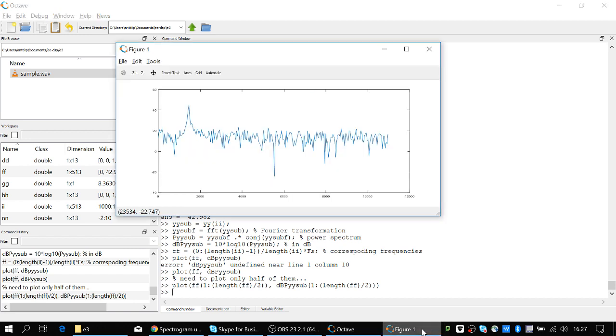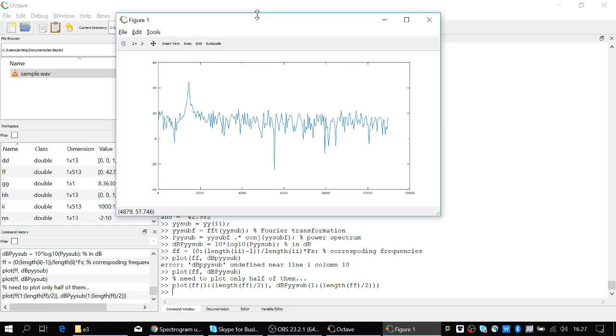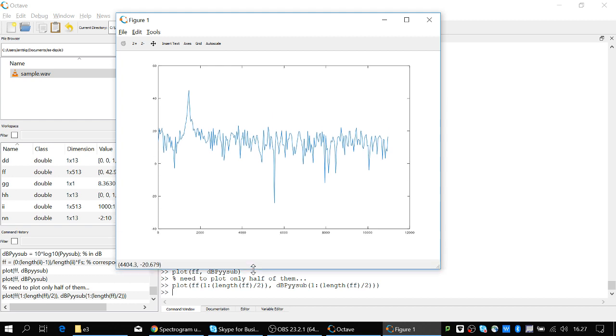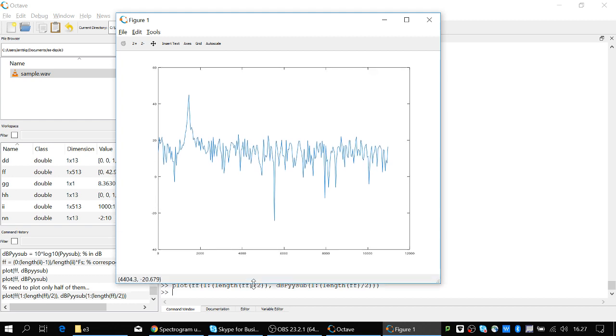Okay, so that's the spectrum in decibels, unreferenced decibels. I didn't put any reference level for this one. On the other hand, it doesn't make any difference. Usually when you have a data acquisition system, unless you calibrate it, you don't really know that value in any case. And if you want to calibrate the system, then it's just a simple addition here, referencing.